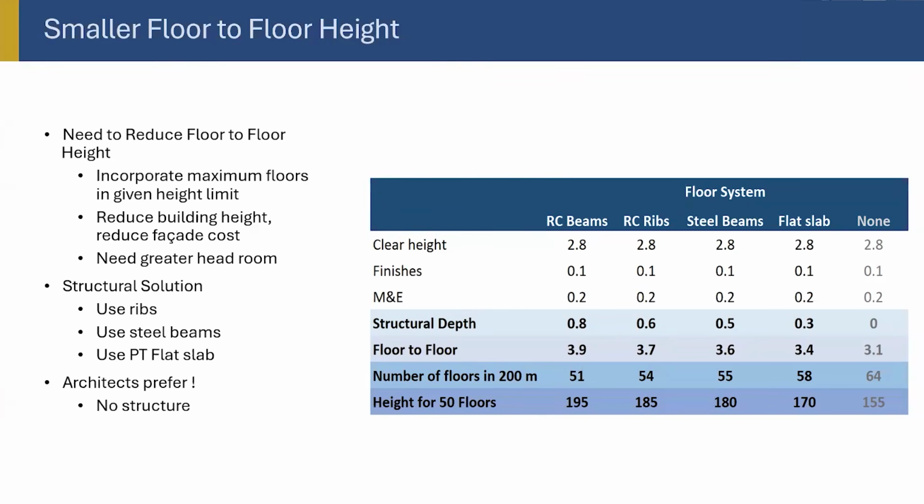Any reduced number of floors means money. Any lost space in structure means lost money. So ultimately, it's all about how much the client can sell, how quickly they can sell. So structural system selection is no longer based only on structural thinking. It has to be much bigger than that.